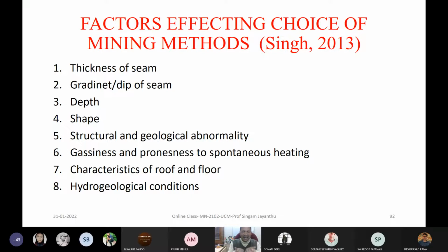I blast on the sides, and if it is inclined like this, whatever I blast, this material will flow through that gallery to the lower level. That is what breast stoping means in a metal mine. In coal mines also, if it is steep, we can do it in that way. Just blast it, and that material will flow on its own to the lower levels. From there you can collect through a chute and so many things.